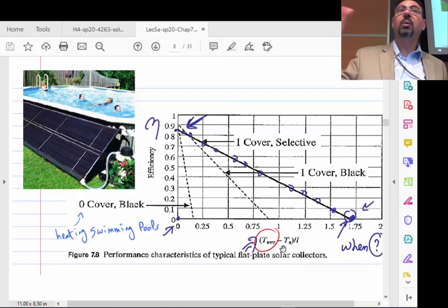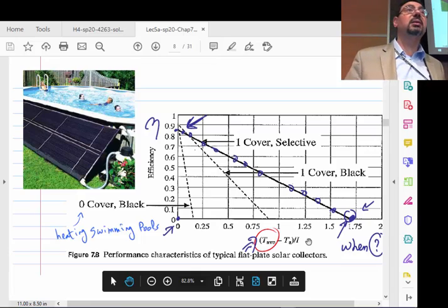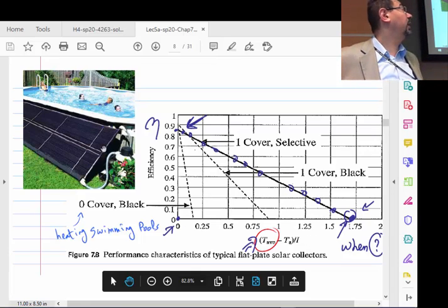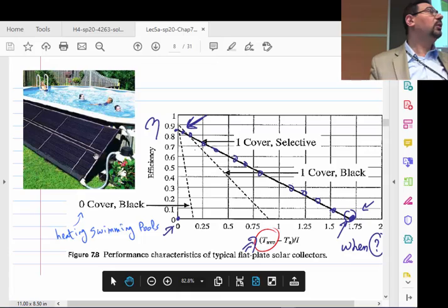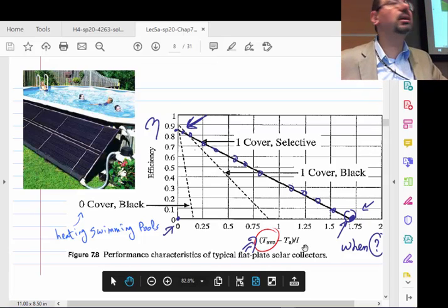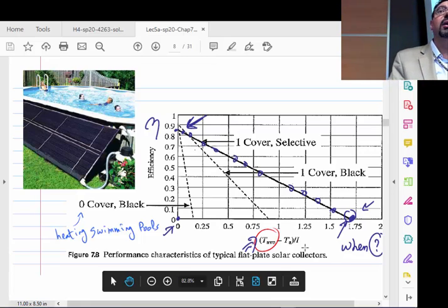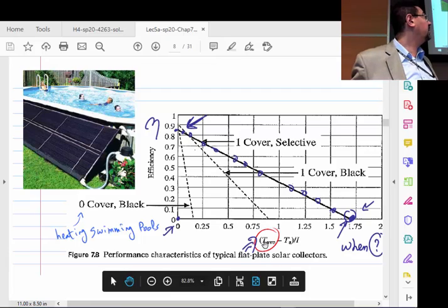I can just Google what's the average temperature in December, January, whatever, right? The incident radiation also exists, especially if you know the tilt angle. You're going to hang this on the top of the roof. You know that at 45 degrees, the roof is tilted 45 degrees, you'll be able to get this I. How much is watt per meter square on a tilted roof? But what's really hard to get is the T average.